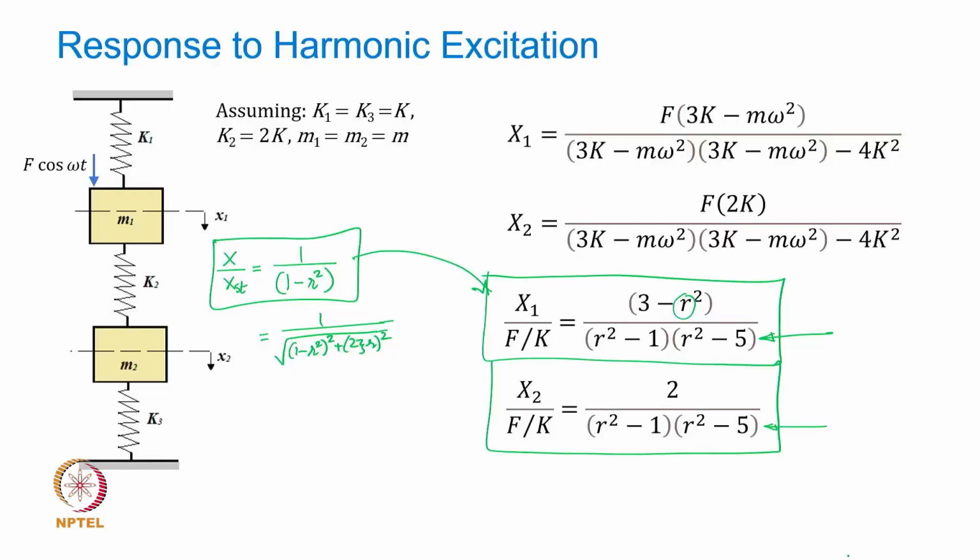Similarly, when they are at resonance, all the mass elements of that multi-degree of freedom system will also have large amplitudes. Relative to the other frequencies, they will reach their maximum value. Of course, in some cases, depending upon the mode shape, some amplitudes will be 0, some of the masses will simply not move. We have seen the node position, but the resonance applies to every mass element in that multi-degree of freedom system.